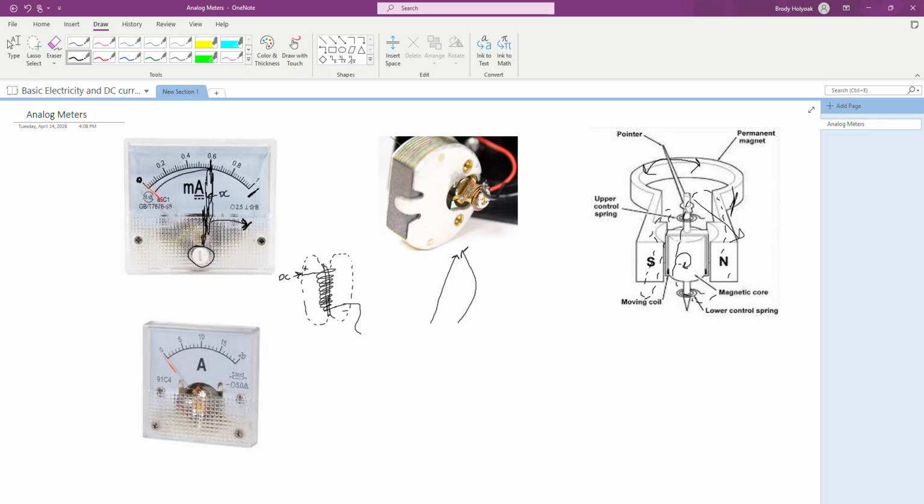One of the other things that you're going to notice, this one doesn't have it, but there are times when we have scales, and underneath you'll actually see this little metal reflective part. So we'll have it there, and then we'll have our scale that goes from 0 to 10 milliamps or whatever, and then it's got the different markings going through, and then you've got your needle that's pointing up like this. Well, what happens is because right underneath that line we have the reflective surface, depending on how you look at it, you can actually create a phenomenon called parallax.